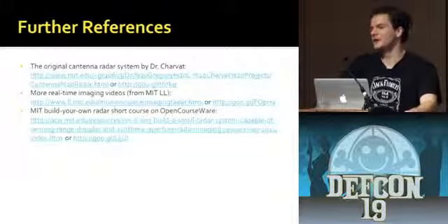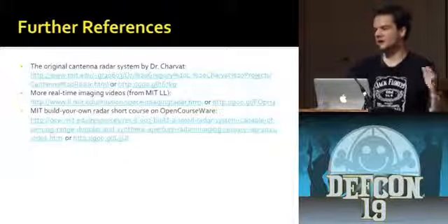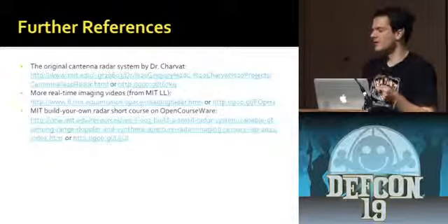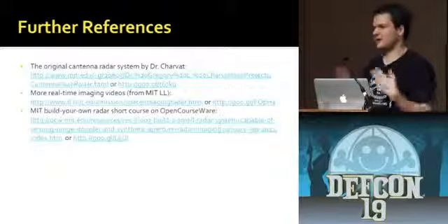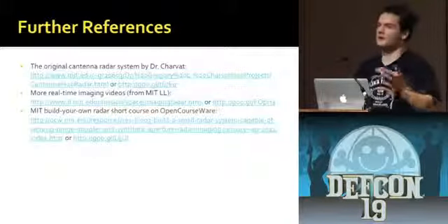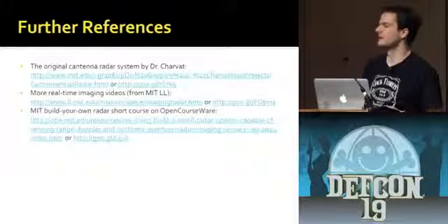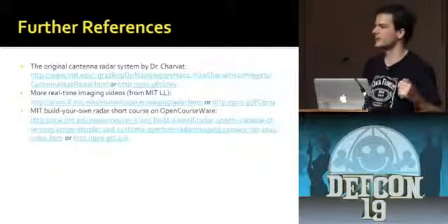On that microcontroller, it would be pretty hard. The processing power on this thing is pretty weak. It's just useful for quickly grabbing data. If you switch to a DSP or a nice ARM or an FPGA, that would probably be the best option in that regard. You could definitely do that. It's not a very computationally intensive process. I mean, this is a Python script I was running to do the FFT.